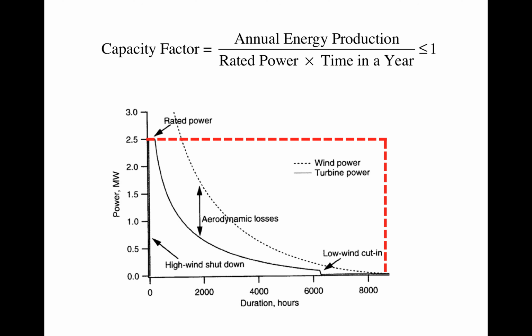One is the power curve of the wind turbine, which can be computed using the BEM theory, or is supplied by the wind turbine manufacturer. The other factor is the wind characteristic of the site, and we talked about how to characterize the wind using either direct wind speed measurements collected from anemometers or statistical methods based on the Weibull distribution.